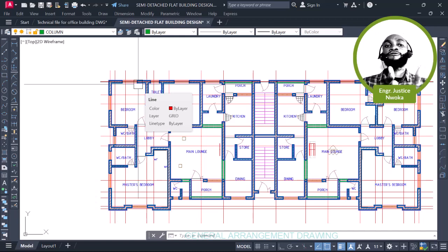But for this design right now, for a normal design, the most common shape of column used is a square column, or a rectangular column. But the square column is the first column shape that should come to your mind whenever you are performing your structural design. It is when it is not sufficient or when it fails that you can go and choose a rectangular column. So we are going to begin with a square column.